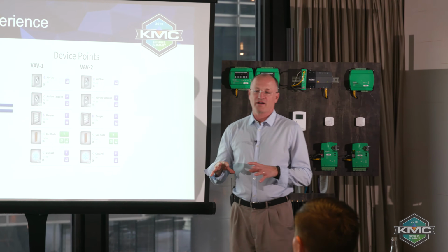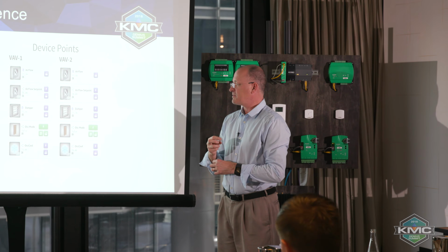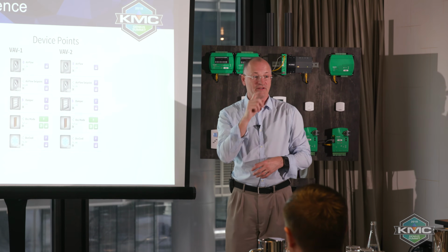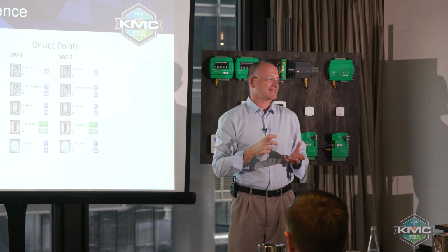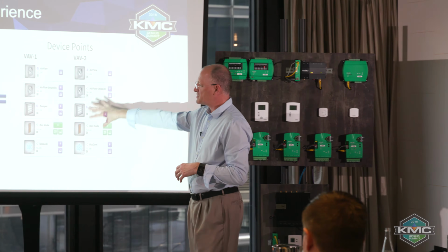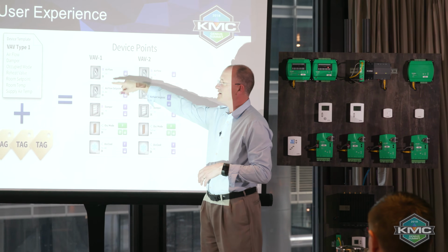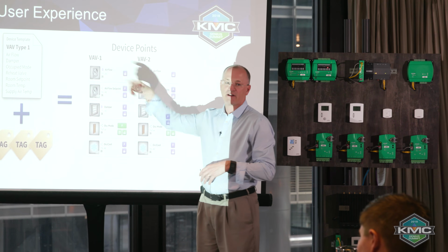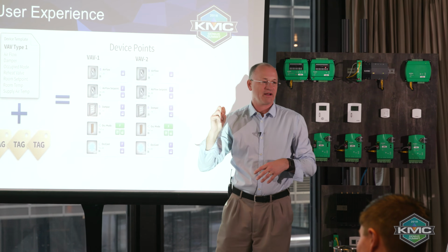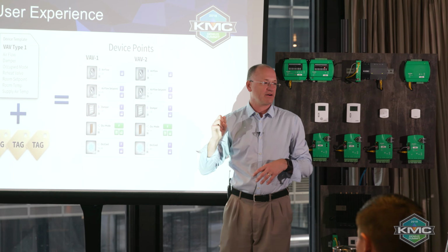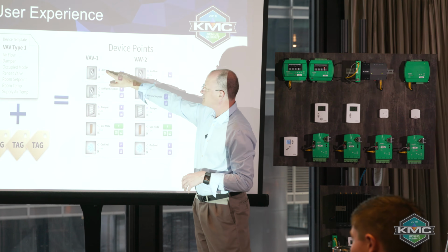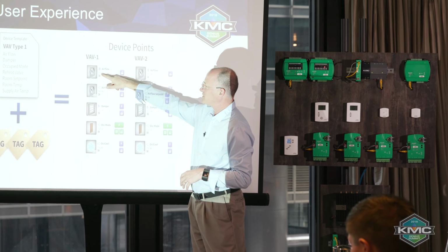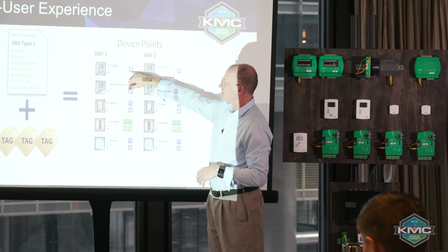Now, don't get me wrong, this sometimes scares people because they're like, wait a minute, what if I screwed up one of those tags? And most of the software will degrade nicely. So in this case, if I didn't really have an airflow sensor, I just grabbed the data right out of BACnet or grabbed it right out of Niagara, this would degrade nicely. You'd still see airflow, which is the display name. You'd still see the value. If it had history, it's still there.